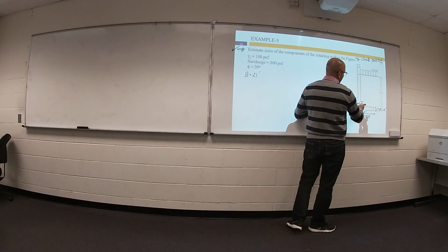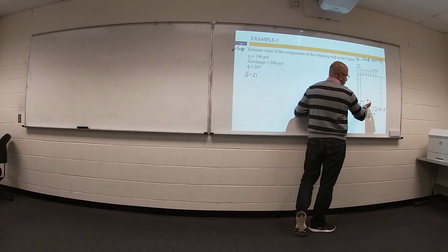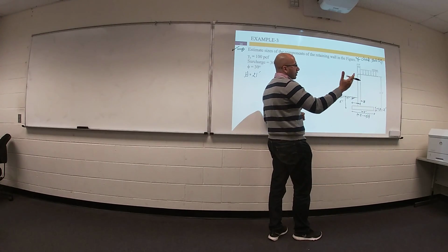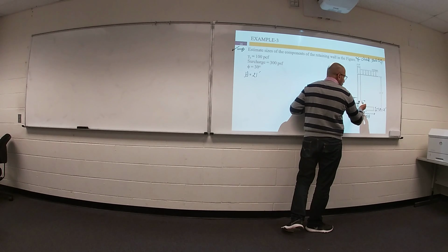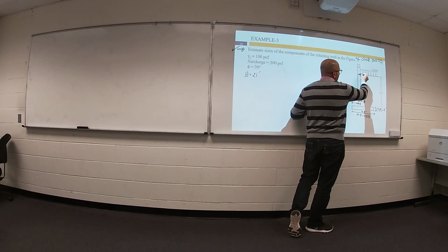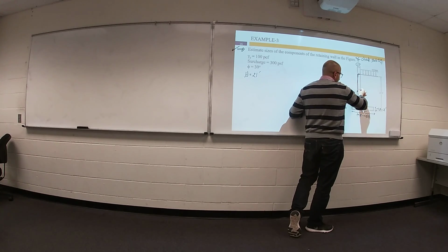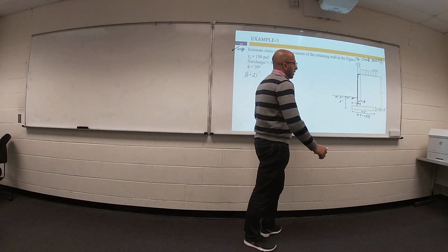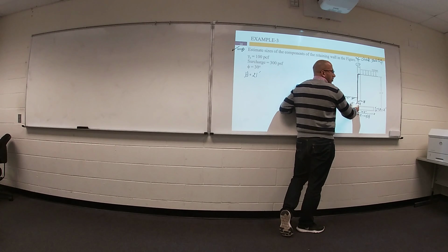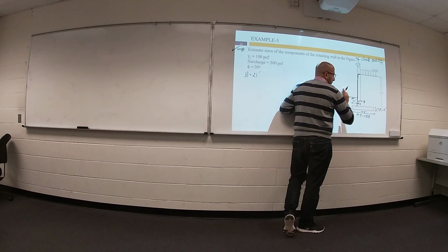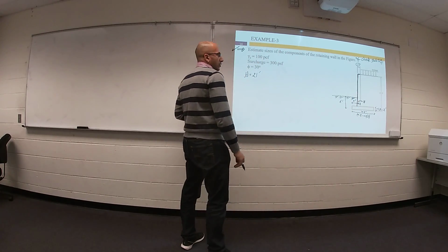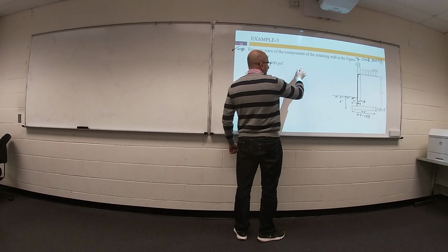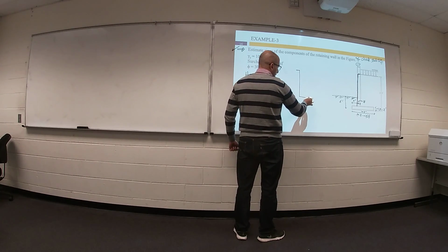And I will assume this one 0.1 h, so that means I have to assume this one 2 feet. And this one is 1 foot as given, so your thickness should be variable like this. What about this term? How much? Is it 0.1? Yeah, 0.1, so 2 feet also. So the final shape of the retaining wall is something like this.